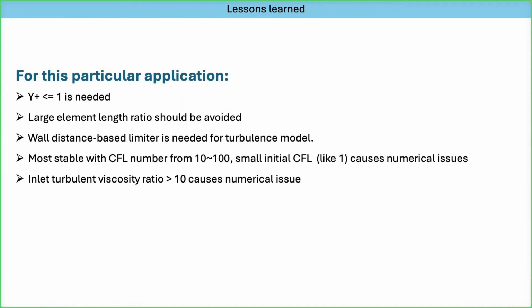I'll quickly go over a few lessons. For this particular application, a small y plus less than 1 is preferable, and large element length ratio or element growth rate should be avoided. These are just common criteria for wall resolution.